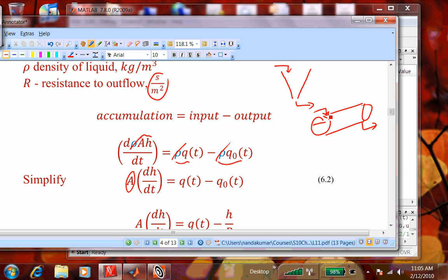No. It still depends on the order of the derivative. Okay, so it will still be governed by a first order transfer function, but we would call that, I think I introduced the terminology earlier, linear time invariant versus linear time varying. I think you asked the question for clarification, right? So if any of the coefficients here are changing with time, then you have a linear time varying system. Okay? It's still a linear system, and it's still a first order system.